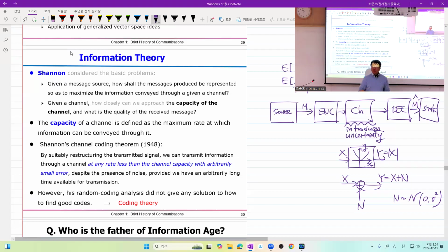And one of the ways to model that kind of thermal noise is to model the noise as additive Gaussian noise. Of course, in some cases, modeling the noise as additive Gaussian noise is very dangerous. However, we start from the simple model, and the simplest is to model the noise as Gaussian noise. So if you take the digital communications course, probably Professor John Joseph, when he first introduces the communication channel, will talk about the additive Gaussian noise channel.